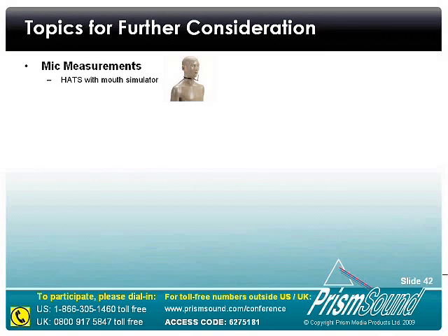Now, as you'll be aware, as I've explained, we haven't actually made a microphone direction measurement here today. We focused on the headset earpiece transducer, and as I said, we do need to employ a head and torso simulator with a mouth simulator in order to make the microphone direction measurement. And there are some subtleties associated with making that kind of measurement.